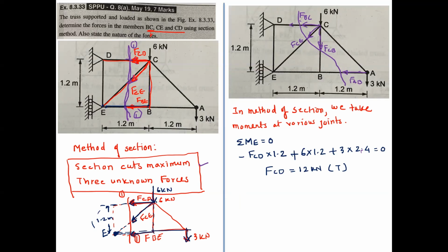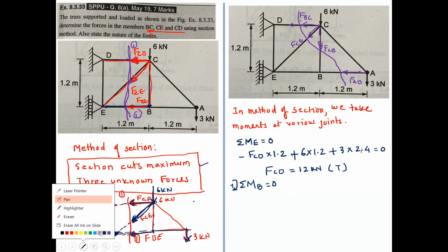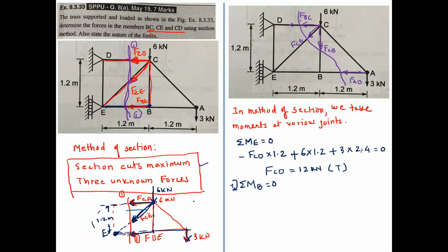Check this. This is your other force, FCE. To find the force in this member, you can take the moment about point B. If you take moment about B equal to 0, clockwise positive, you can resolve these forces into components.